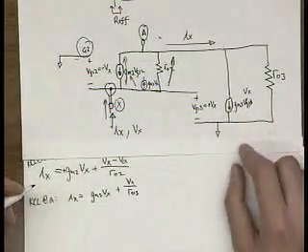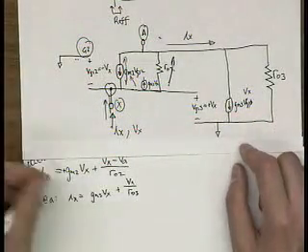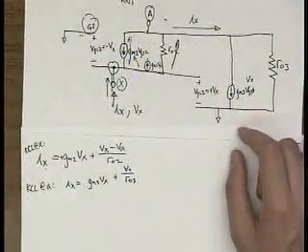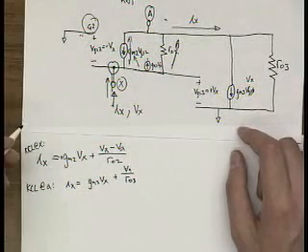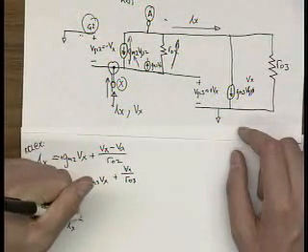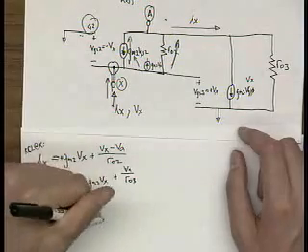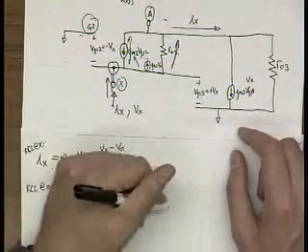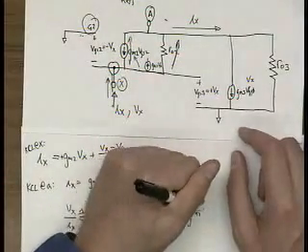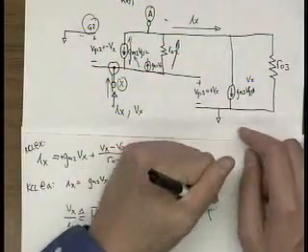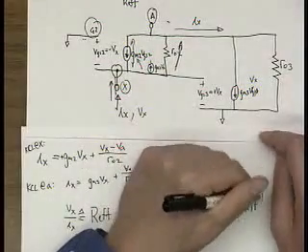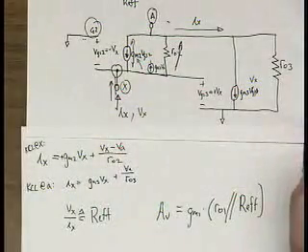Now, because I want to get to the project and start talking about that, I'm not going to solve these equations. Okay? Solving these equations is relatively straightforward, and you can end up getting Vx over Ix is equal to R effective, and then the gain itself is equal to GM1 times (RO1 parallel R effective). Okay.